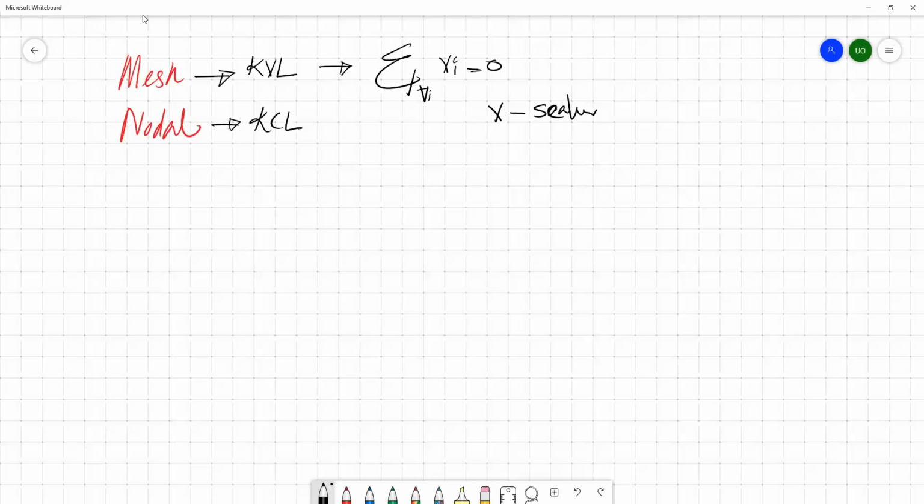but depending on the direction in which we apply Kirchhoff voltage law, it may be clockwise or anti-clockwise. So we can introduce plus or minus in front of each voltage. If it is a plus quantity, we assume the voltage drop is in the direction we are referring to. If it is a negative value, with a minus sign, we consider it in the direction opposite to the Kirchhoff direction.